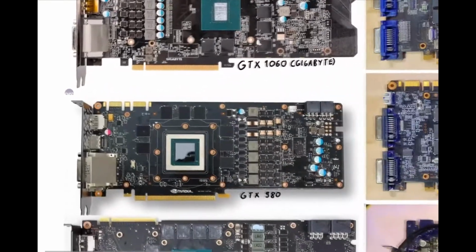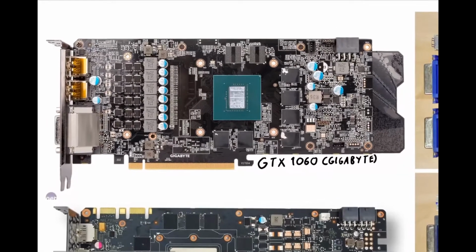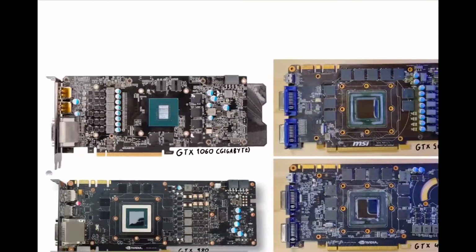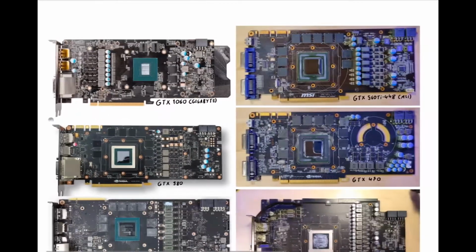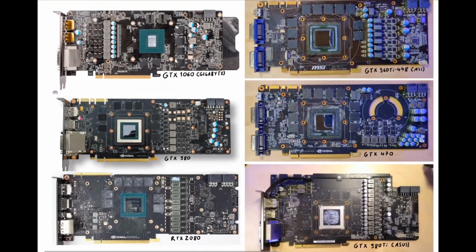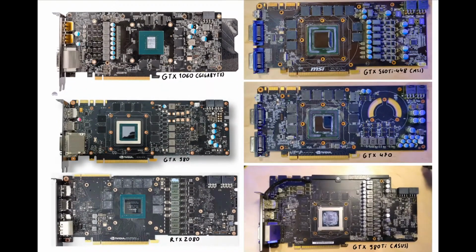Then there are some less constant things, but these will also always be there, which is first the power connectors and your video out, and the PCI Express slot, of course. All of these cards have those three things. Certain graphics cards that are really, really low power do not have power connectors, but if you have one of these cards, why do you analyze the PCB of it? Because obviously it's not really meant for overclocking. So yeah, there we have the power connectors of all the cards. You can see there are two different versions also. There are 8 pins and 6 pins.